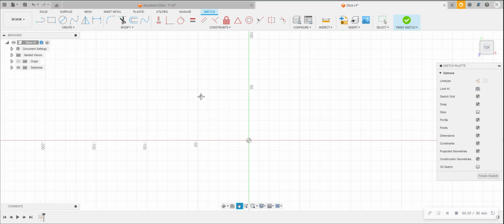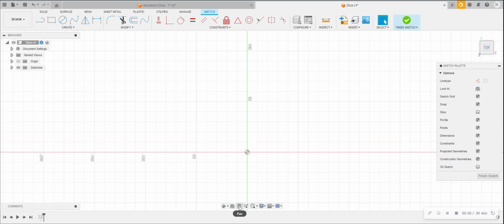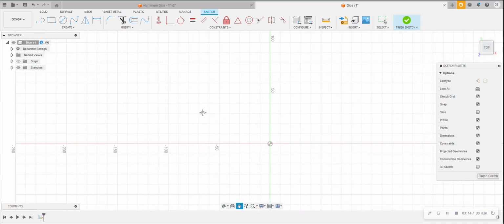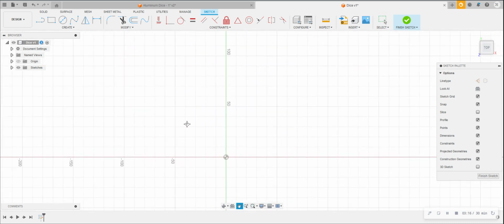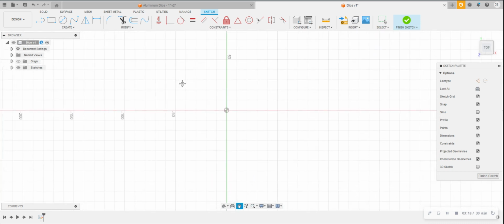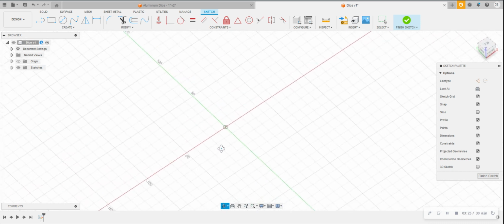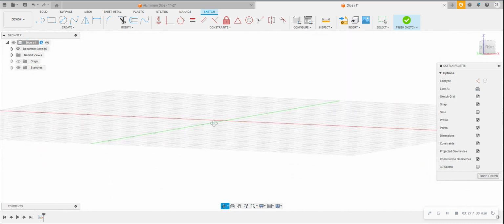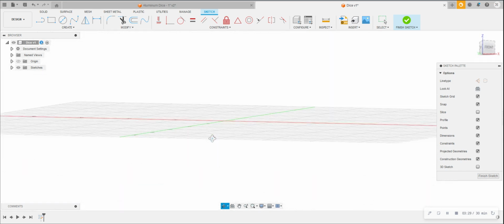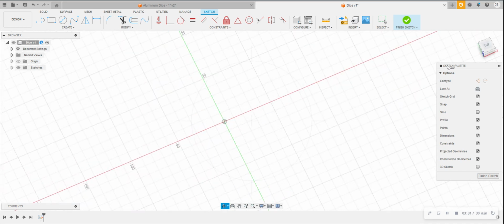And we are going to just pan the drawing down. Now there are commands down here. You can see where my cursor is. It's hovering over pan. If I click that, I can move the sheet or the area that I'm sketching on around. I can also use this tool over here. This is called Orbit. So if I wanted to manipulate something in 3D and look at different angles of it, I can use the Orbit to do that.